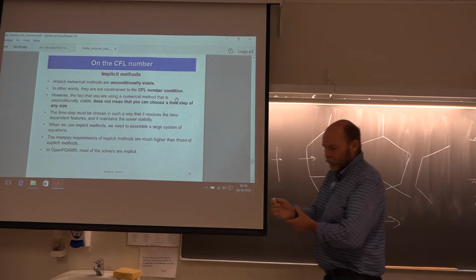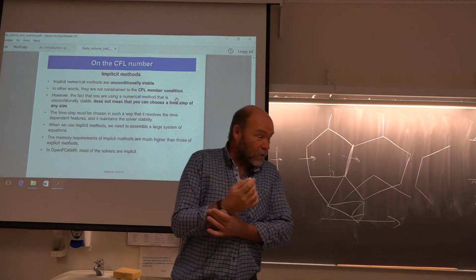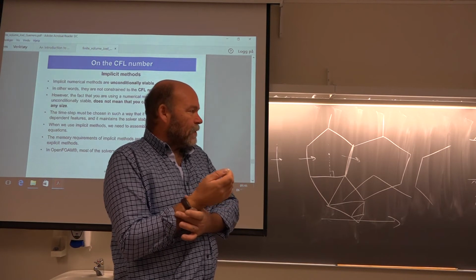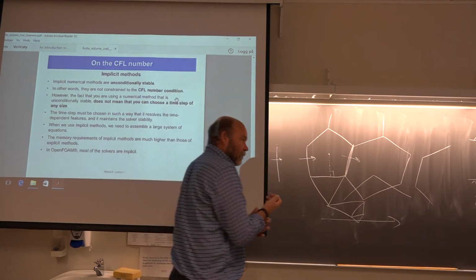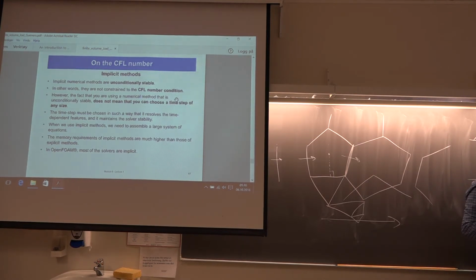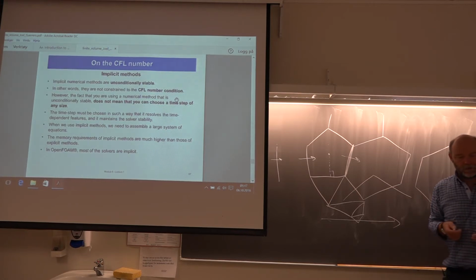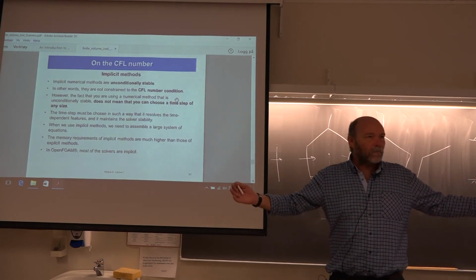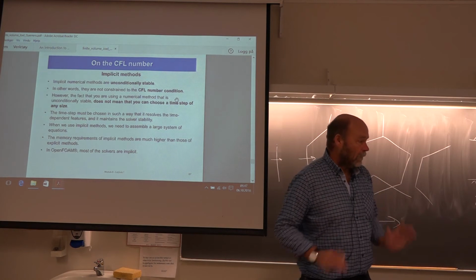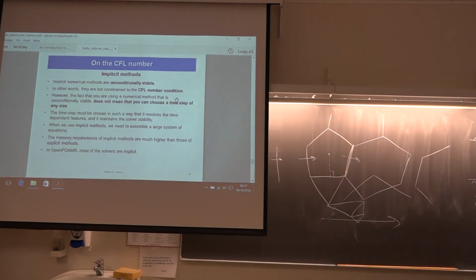So we just have to solve the Navier-Stokes in time and space to find it. If you had chosen an implicit method there, you could have taken a time step quite big. So big that you actually skip the physics. I mean, remember this frequency, that is something that Mother Nature decides. It's not for us to decide. And then if you take a very big time step, then you don't see this frequency at all, or you get something very, very wrong. So, implicit methods, careful.